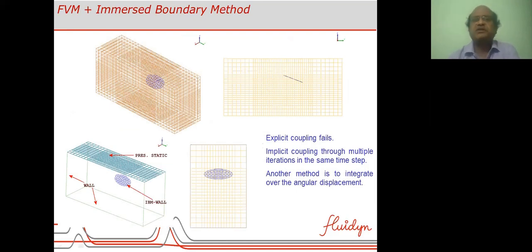It's a Cartesian mesh, the structure, and you can see that the fluid mesh does not conform to the valve. It is made without considering the valve. Then later, a surface mesh is generated for the valve independently, and they are integrated. For example, in Fluent GUI, you can load multiple meshes. You can load a fluid mesh, and you can load a structural mesh, which is created separately.